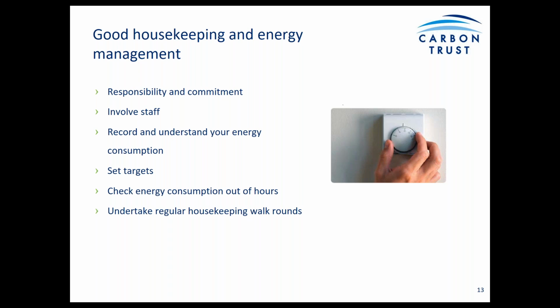And finally, ensure to undertake regular housekeeping walk rounds. So just make sure that walk rounds are carried out within the building or on site at different times of the day, just to get a better idea of where and when energy is being used and potentially wasted. So look at different patterns of energy use throughout the day, and then note down and act on any issues that have been noted, for example, any maintenance measures that might be required.